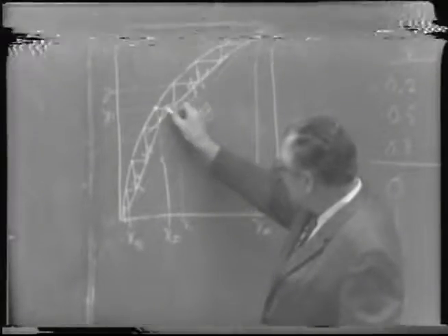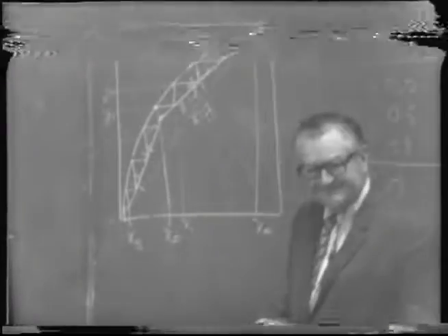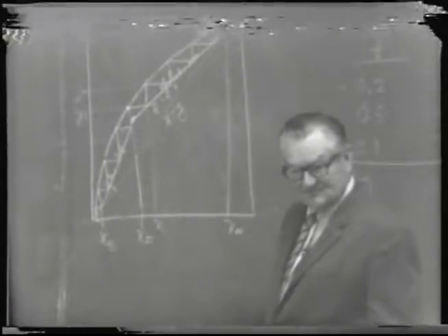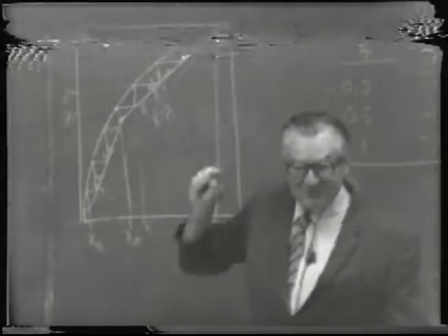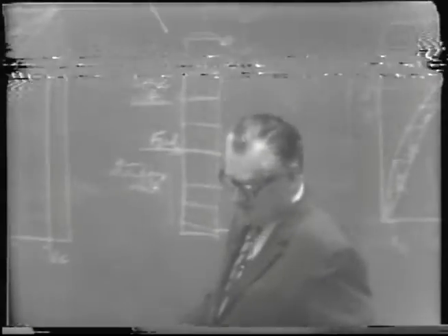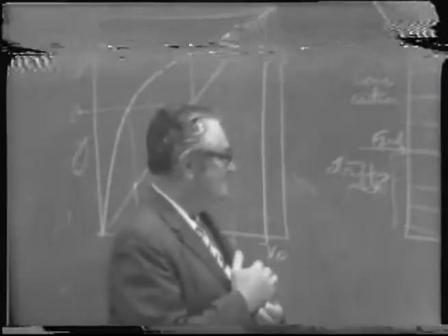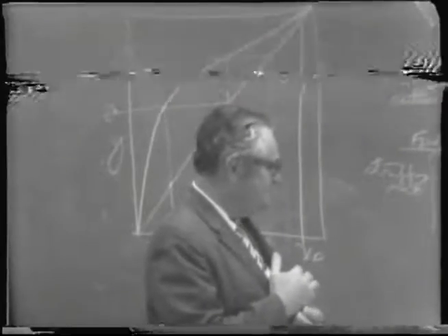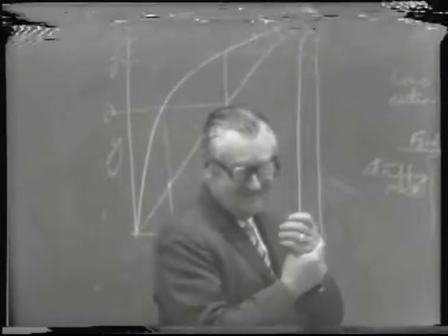In other words, I could stop drawing those at that point, you see. You frequently draw the lines on beyond the point at which they apply. So to find the Y, you take from XF all the way up to the equilibrium line, and then you draw over to the operating line. I hope this will become clearer after our next period or two.